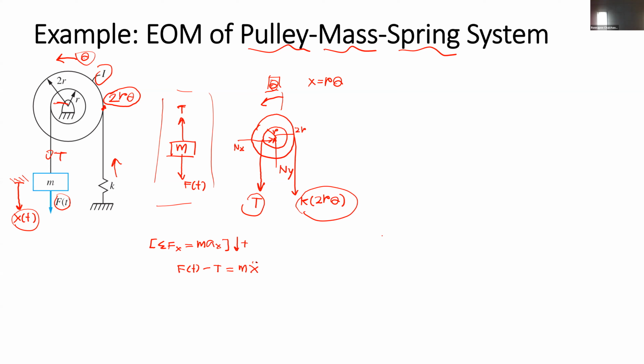For the pulley, it's a little more complicated if we consider the forces, but we're going to sum the moments about point O. Let's assume here is a point O at the pin location as the rotational axis.